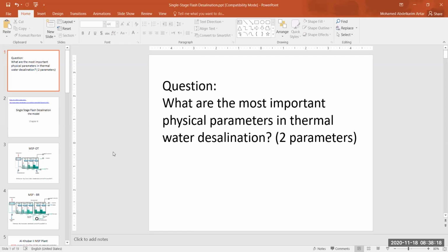So even when you think of the HDH unit, if I'm able to reduce the pressure in the humidifier at a given temperature, then I can produce more vapor to be carried by the air to condense in the condenser.